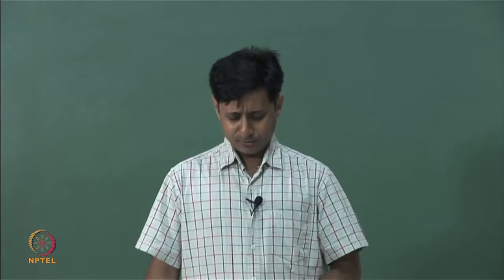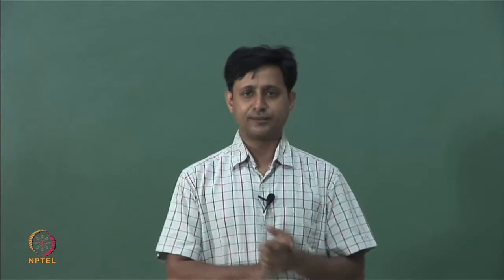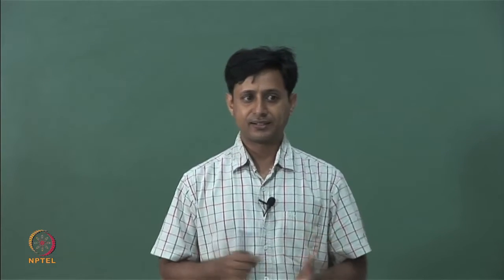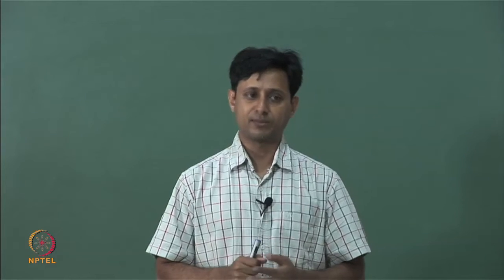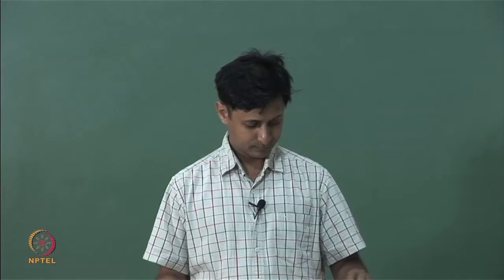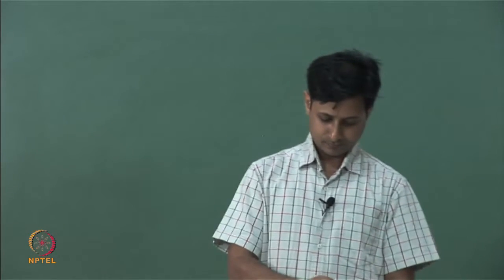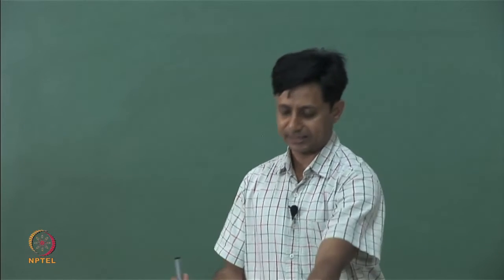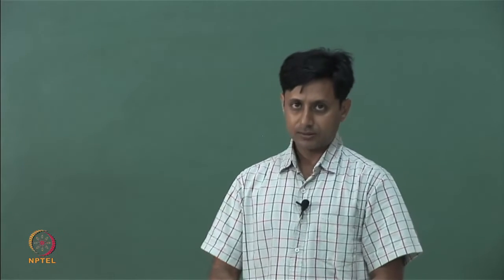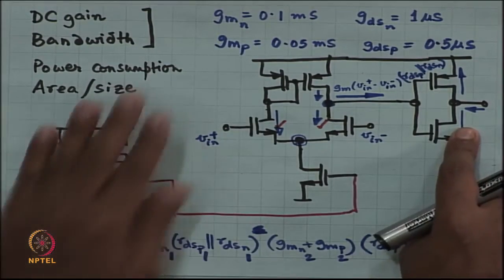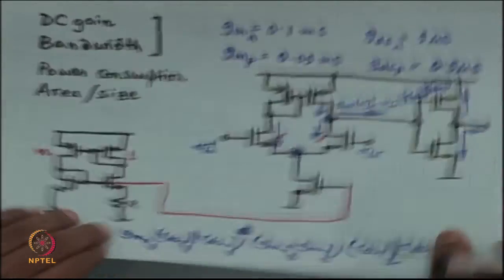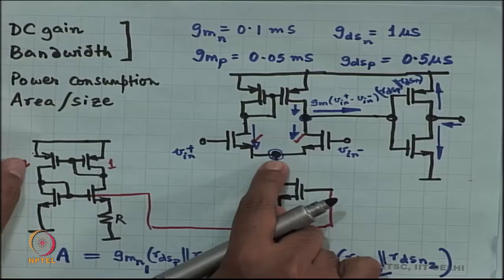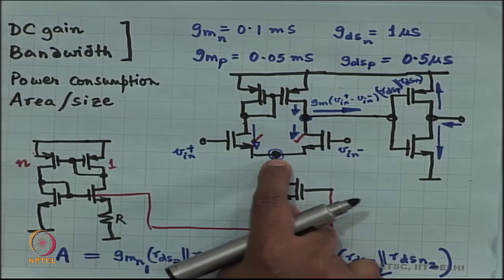Okay. Now, let us say you have got this gain of 5000, then you say that all right, now I need to make sure that my phase margin is 60 degrees. How are you going to do that? So, how will you work out the phase margin? So, let us simplify the circuit and redraw this differential circuit with first stage, second stage. So, after simplifying and redrawing, basically what am I going to do? I am going to assume that this node is at some ground, right.